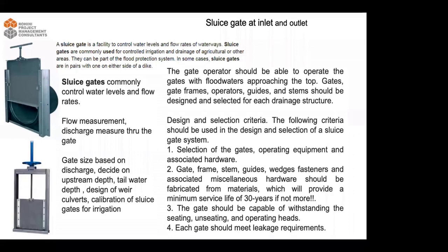Because obviously, as we say, water finds its way, right? So there are leakages that have to be taken care of. Specifications are needed to maintain the leakage under the seating head. Now, it is recommended that each gate be well equipped with adjustable wedges.